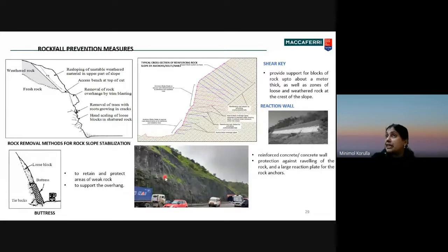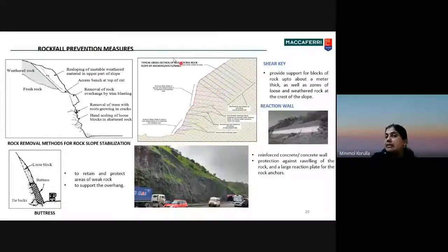Okay, so the Mumbai Pune Expressway, with all the drapery system and deep nails, which prevent the global stability problem as well as the superficial stability problem, that was done. And apart from that, a lot of drainage measures, subsurface drainage measures, are being provided. So this rock slope at present is stable, but it is a combination of the nails, the surface protection drapery system and the horizontal drains.